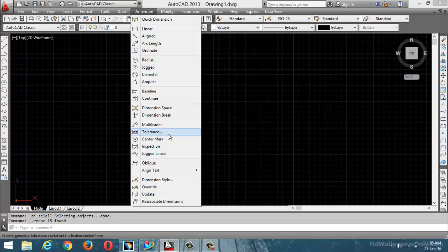Again, this tolerance is related to mechanical. While manufacturing any component, first we need some draftings, nothing but production drawings. At the time of production drawings, we can use some symbolic representations. You can design anything, you can manufacture anything, you can set some limits, tolerance values. You can represent entire tolerance values in the tolerance table. Then you can assign the tolerance table to geometries. The command is TOL. Tolerance command is TOL.